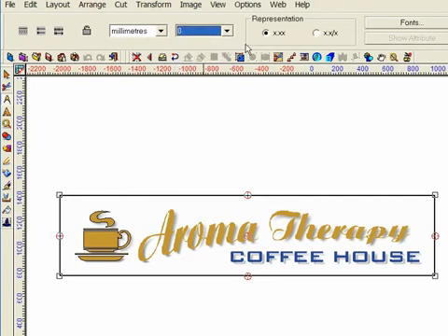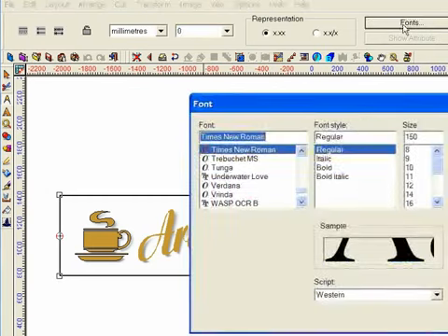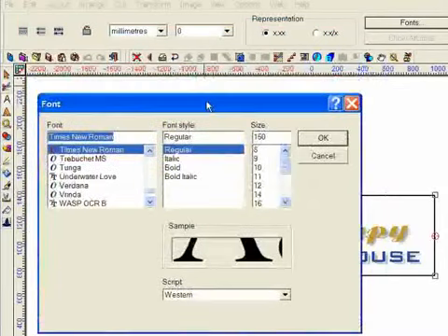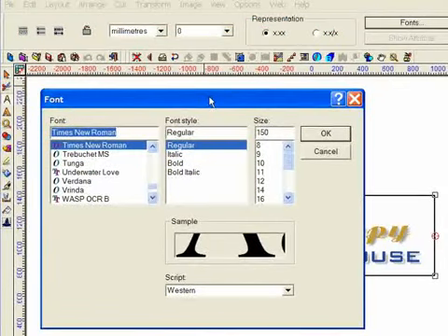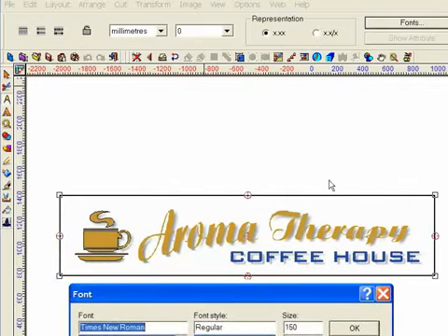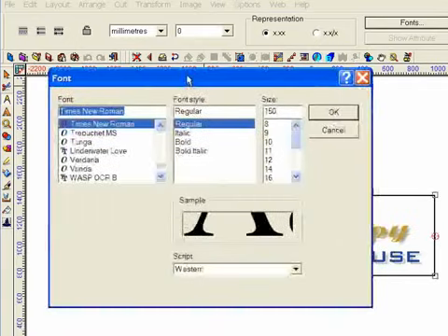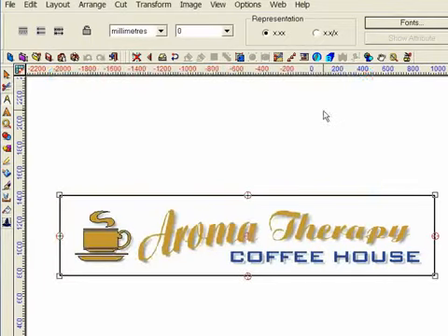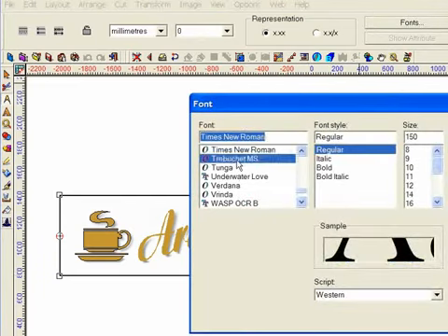I will need to define the font that my measurements are displayed in, and the size of that font. When considering a font size, it's important to make an account of the actual size of the object that you're adding dimensions to. My sign is 3 meters wide, so I will need to use a relatively large font size to ensure the dimensions are clearly visible on my finished visual. For this example, 150 should do it. As you will see, the font to be used can be changed here to suit your preference. I'm happy with the settings I have made here, so I will now click OK.